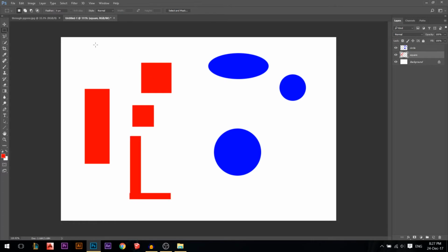Okay, let's say I want to draw a square with a hollow square inside of it. So I drew my square. Now I want to minus a part of it. So instead of pressing Shift, which is plus, I'm going to press Alt or Option, which is minus. And then I'm just going to draw another square inside. Now I minus this selection from the total. Now if I color, we colored only the outside part. Okay, everything is looking good for now.